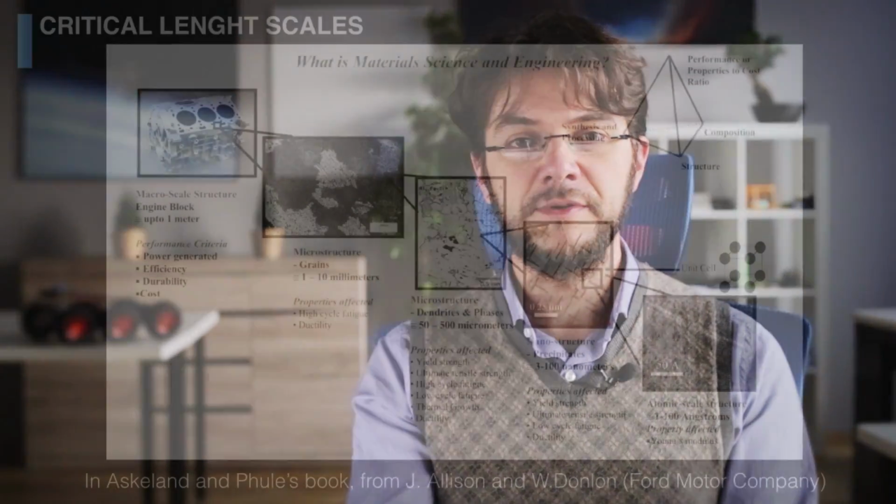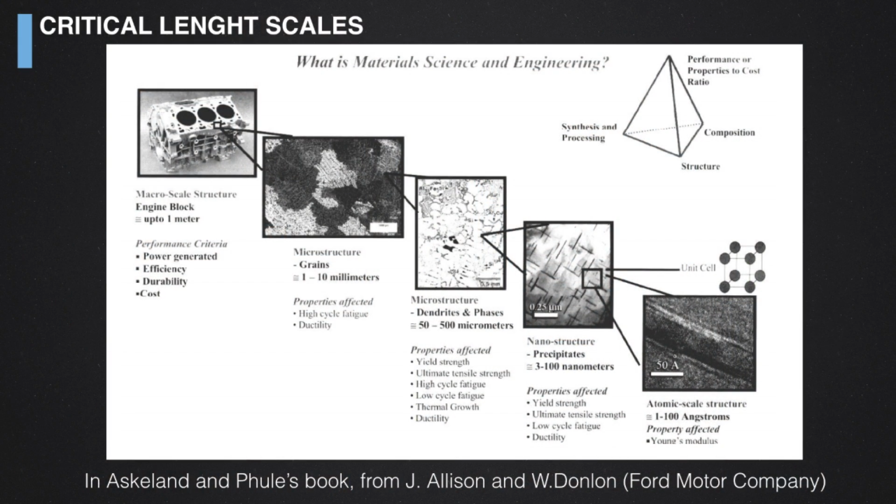You may try to structure those inclusions, so give those inclusions a preferential crystalline structure and direction. And if you're able to do this, you will achieve another key, another means to increase the mechanical properties, for example, along a certain direction. And if you go to the atomic scale, you will see that the grains are composed by single atoms.